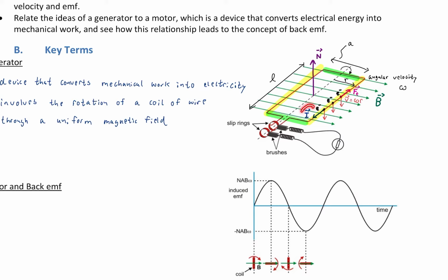So we can see that the current is going to move in the clockwise direction because the electrons are going to experience a force in the counterclockwise direction. That's just because, of course, electrons move in the opposite direction of the conventional direction of current. And we know the electrons are going to move in this direction from the right-hand rule: at this point in time, the magnetic field points to the right and the electron sitting in that wire has an instantaneous velocity pointing straight down. By the right-hand rule, there must be a force that points back into the page, and indeed, that is the force on the electrons that actually induces the current.